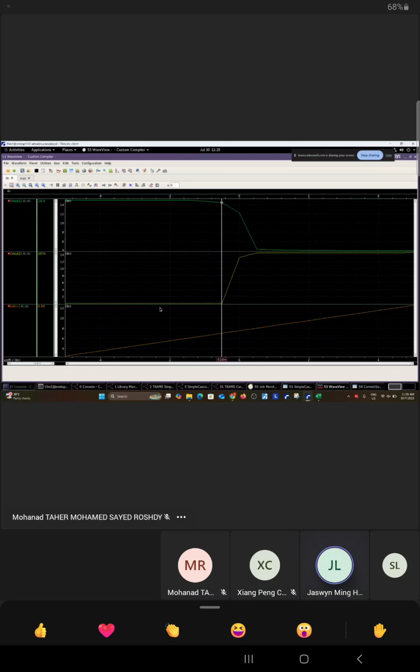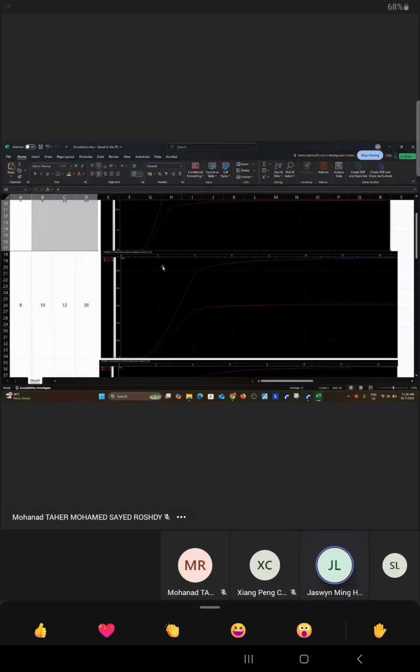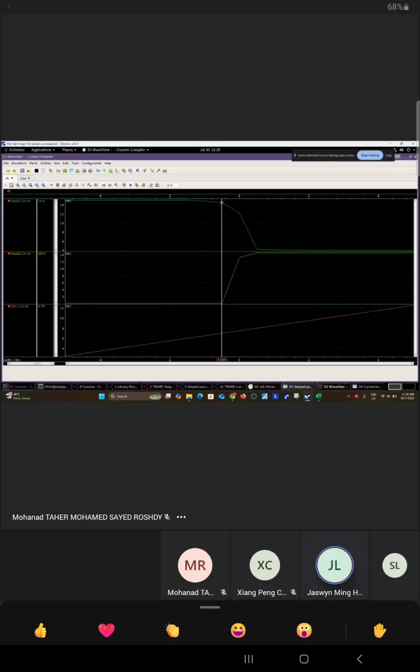I think one thing we can do is just try the different current sources. Actually, I see just now the range is also as wide as this, right? Initially you have the range between 0.5 to 1. Okay, so it's about negative 0.4 to 0.4, similar range. The range actually declines by 0.2 but I don't think that is significant. Well, we just try to change the tail current. You can try, you increase the tail current more.